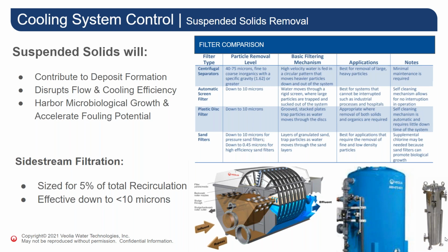Side stream filtration reduces suspended solids and debris in the system cooling water, which leads to less fouling of the system. The picture on the lower left shows a continuously self-cleaning disc filter. The middle shows a typical multimedia filter, and on the right, a smaller cartridge filter.